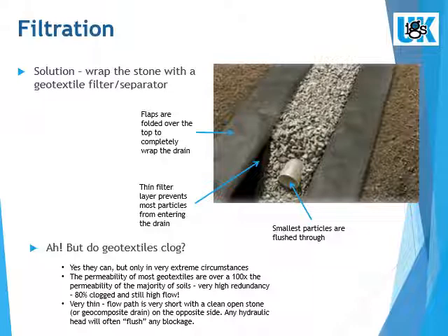Even if the geotextile was 80% clogged, there would be no notable change in its ability to function. As the geotextile is so thin, it will tend to flush with any hydraulic buildup. Maybe a diagram will help us understand what is happening at a particle level.